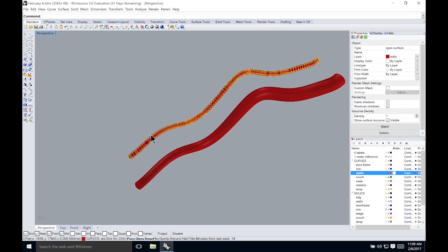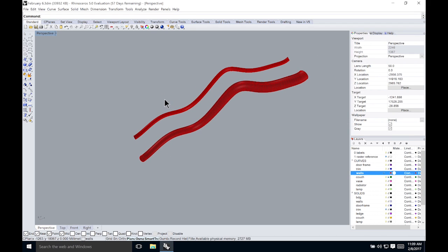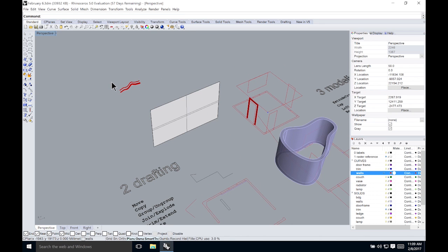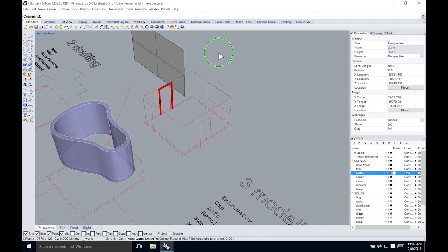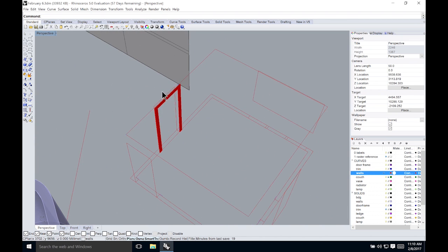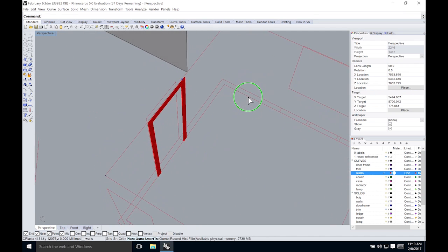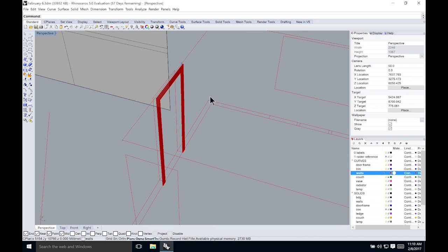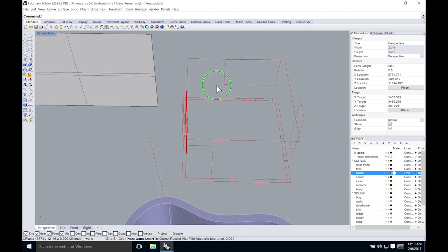But let's say I want to sweep a triangle or some totally other freeform object, and so this command would be very useful for that. And yeah, so in the examples I was using it to create this door frame, which saved me time, because instead of having to create 3 pieces and then use the Boolean command to join them together, I was just sweeping that cross section of the frame around.